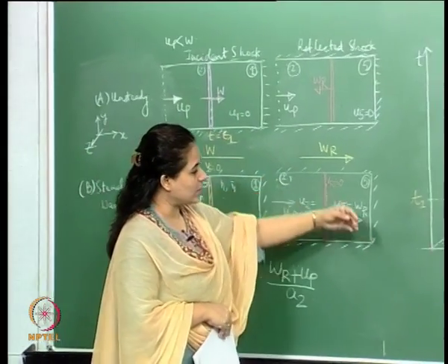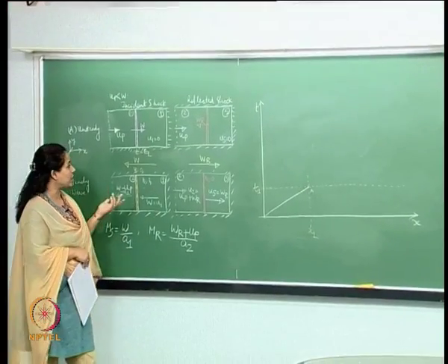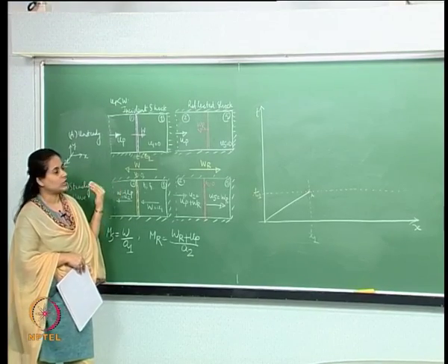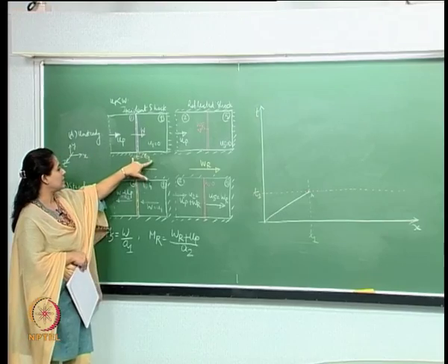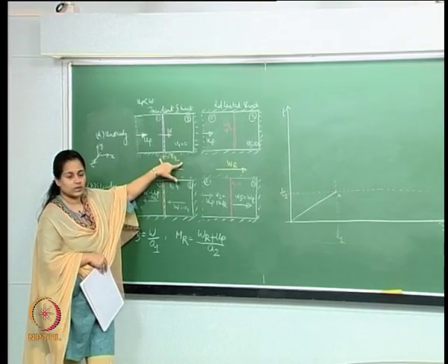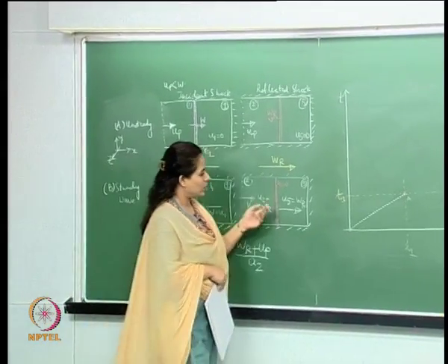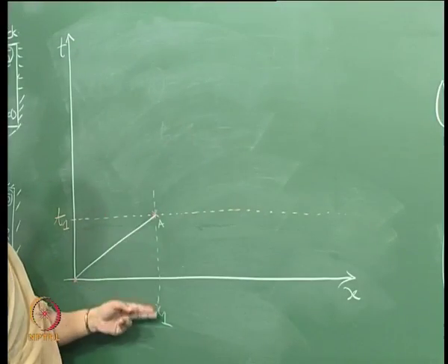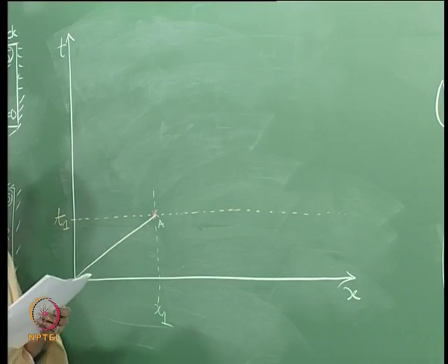At 0 there is no shock wave, and just at that point we break the diaphragm, the shock wave starts traveling, and this is a picture that we are seeing at some time instant t1, when the shock wave has traveled a distance x1. So at time t1 it has traveled a distance x1, so this is the xt diagram.